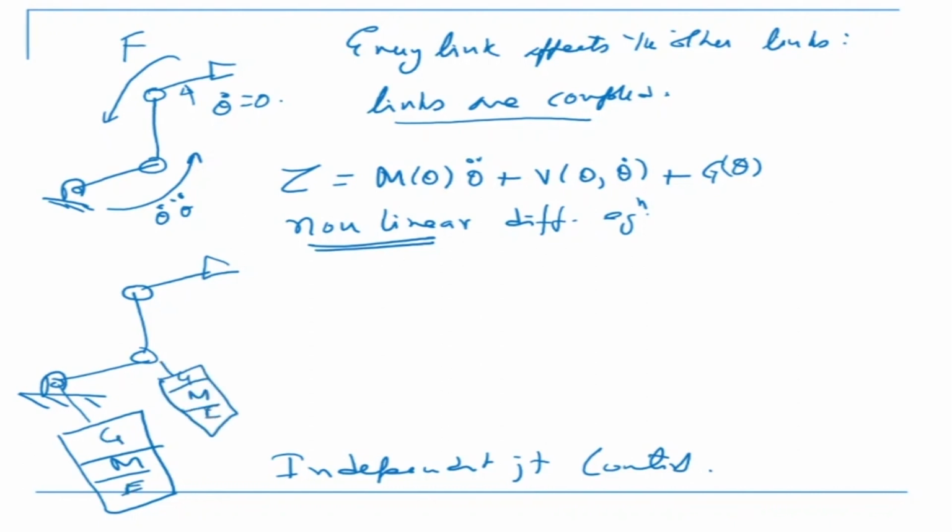Okay, so suppose I want to move this joint by 30 degrees. Only joint 1 will be actuated to move from whatever position to 30 degrees. So joint 2 and joint 3 are independent and they are not affected by joint 1. Whereas in reality, when it is moving, what will happen is the subsequent joints will also be affected by the motion of the previous joint. So what does dynamics do? Dynamics basically acts as a disturbance.